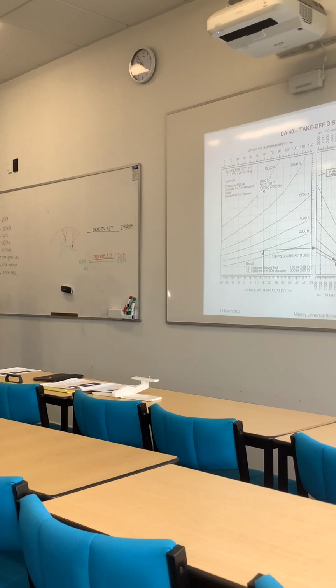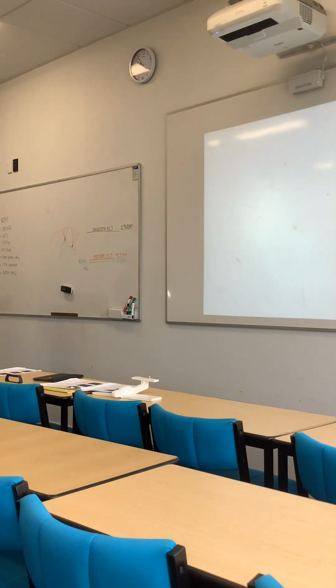Now we actually can plot all of that on the graph. So I'm not going to do that for you guys because you obviously do know how to do a P chart, but this is where you would now take this away, put your lines on there for pressure altitude, and what I would do is just draw it across to the next reference line and stop it there. Then you're going to go into your weight factor. Make sense? Okay, you don't need me to show you how to do that because you do know it, I should hope.